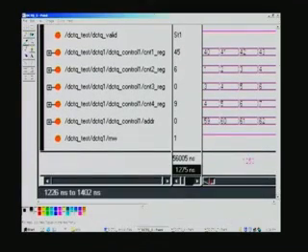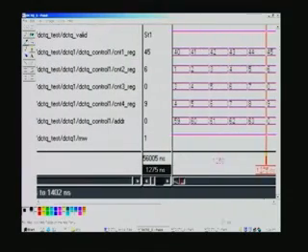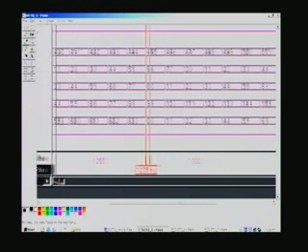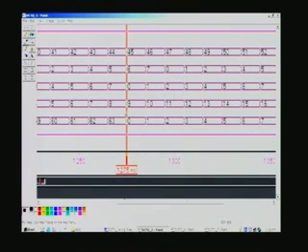In the next waveform, you can see this is the address for the coefficient, and you can see here the coefficient number is 63, which means the 64th coefficient is just now processed, and immediately without any wasting clock cycle it starts processing the second block, next block. At this point of time it is 1275 nanosecond.